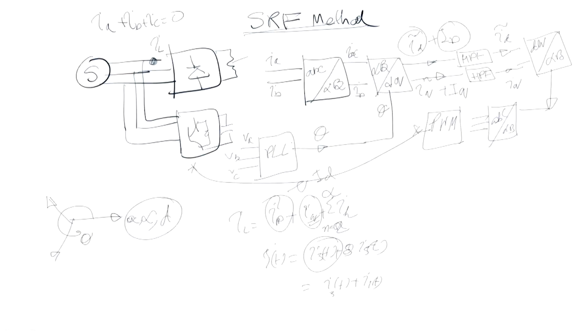So, then we have to generate another sequence, theta and minus theta, so the PLL has to perform differently. Since the D is something that is rotating in a synchronous frame, once you have a positive and negative sequence, the positive will look stationary, but the negative sequence will be rotating at a speed of 50 hertz opposite to you.